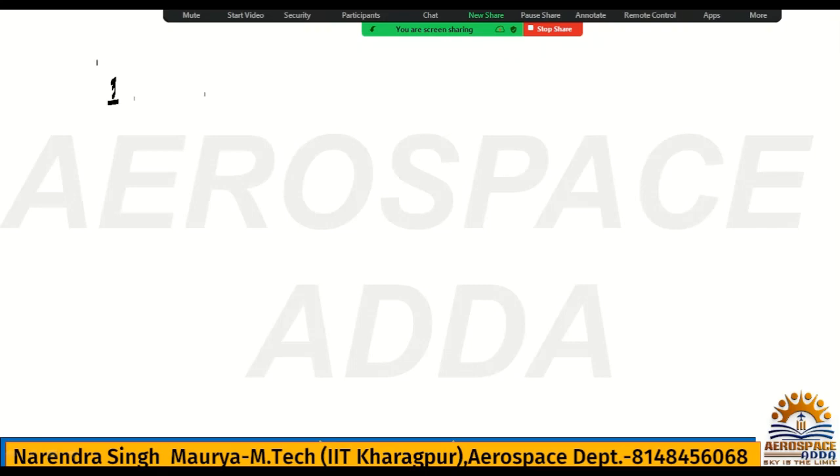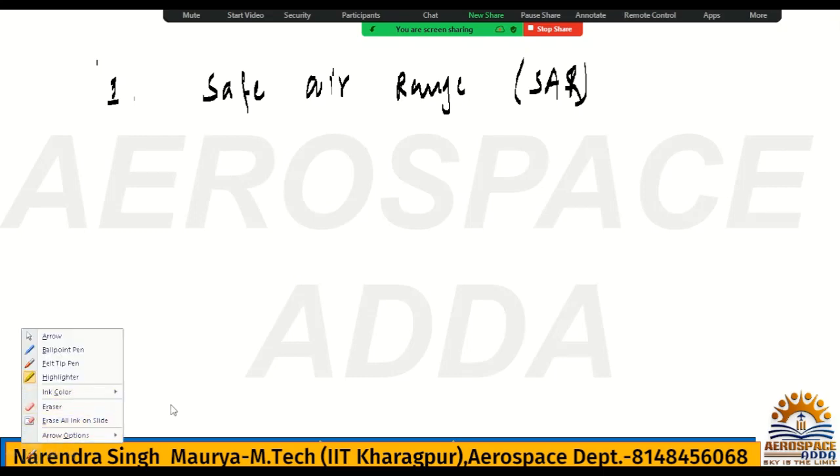First one is safe air range, which is called SAR. What is the SAR? Check the diagram; by the diagram only you will understand. It is the maximum horizontal distance. Listen carefully. It is the maximum horizontal distance that the aircraft can travel safely, which considers the amount of fuel required for each segment of flight, which includes takeoff, climb, cruise, glide, and landing. That will be called the safe air range.